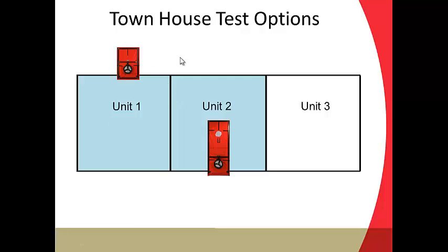If we've got the same pressure in each unit, we've taken away the driving force, so there isn't any air movement across those holes. In this type of test, we're doing what's called a guarded test, or a leakage to outside test, on unit number 1. So we've got unit 1 guarded, and we'll get a CFM to the outside just on unit 1.